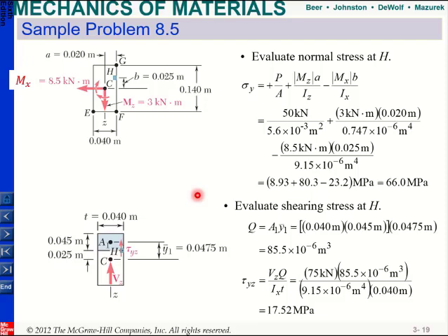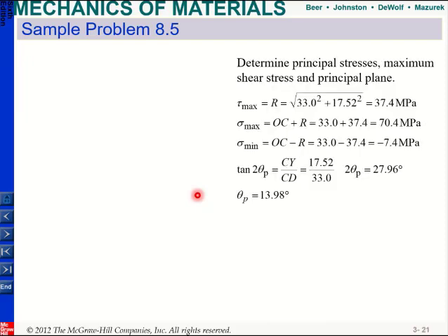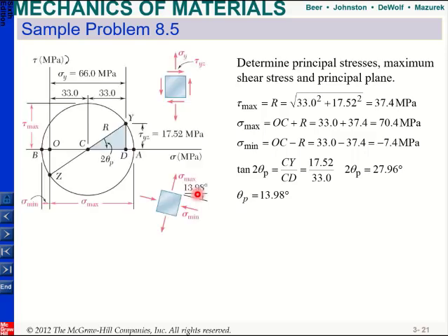So I find my normal stress and I find my shear stress, which means that I can get my maximum stresses. Either you can form your Mohr circle, or you can do tau max equal to R. In this case, you have normal stress minus the other one, which is 0, so you have only sigma y, and only one shear, so you can use this formula to find your R, which will be equal to your tau max.